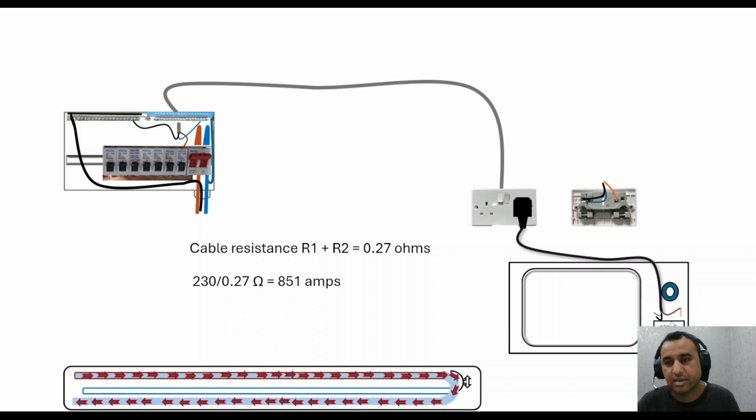It could be a short circuit sometimes between line and neutral, but we're trying to explain when the current flows, instead of short circuit, through the earthing circuit protective conductor, line to circuit protective conductor. This is what we're trying to look into at the moment.